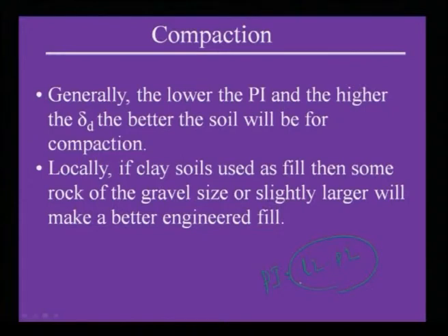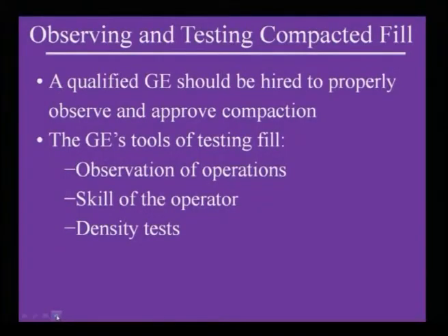Locally, if you use clay soil as a fill material, then some rock of gravel size or slightly larger will make a better engineering fill. That means if you are using this local soil, you mix in some gravel, some stone, so it will make better compaction. A qualified geotechnical engineer should be hired to properly observe and approve this compaction. The geotechnical engineer's tools for testing fill are observation of operations, meaning how the operation has been done and the skill of operators, and density tests. These three have to be maintained.